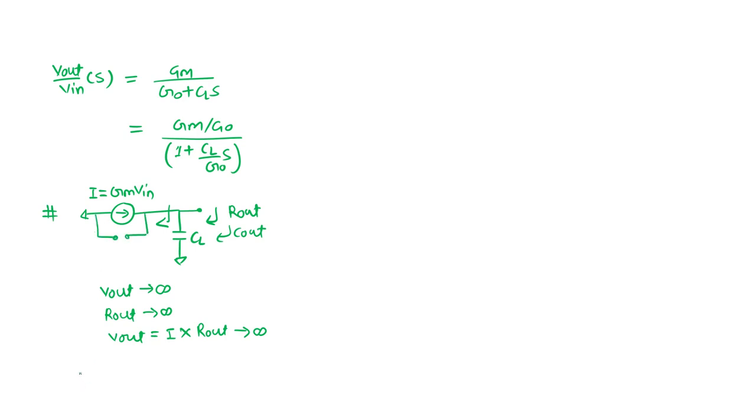So ideally we can say the R out is what? Not R out exactly. What I will say, R out effective, or better to say, Z out should be infinite. Z out should be infinite instead of R out, because R out is a finite quantity, so it is not infinite. The point is that we should make the Z out infinite for making the V out infinite. Instead of writing this R out, I should write Z out.